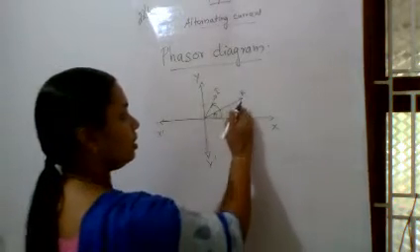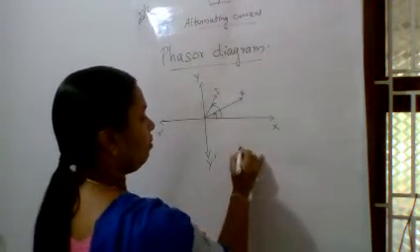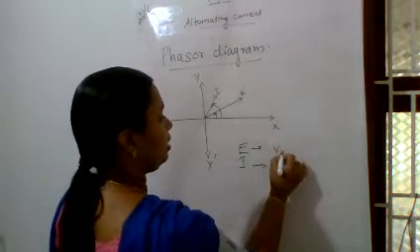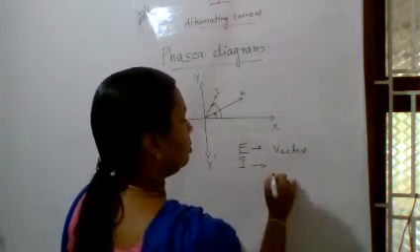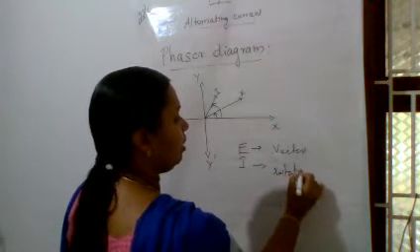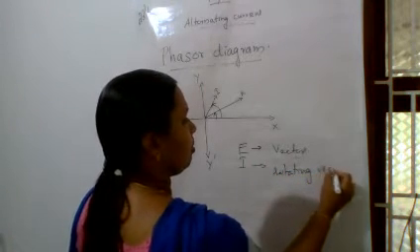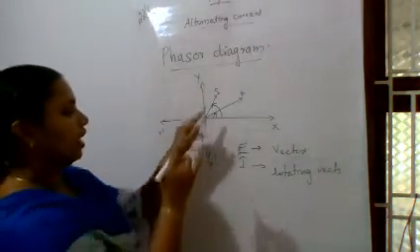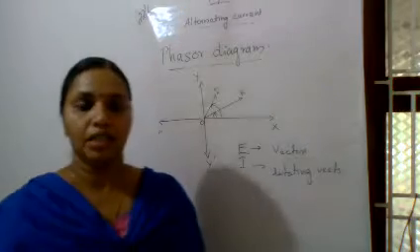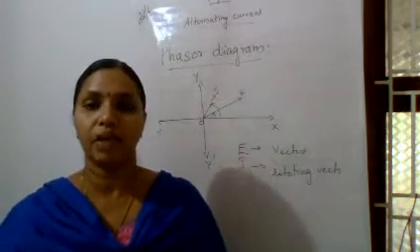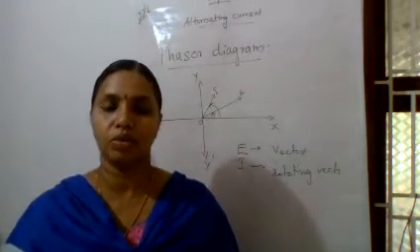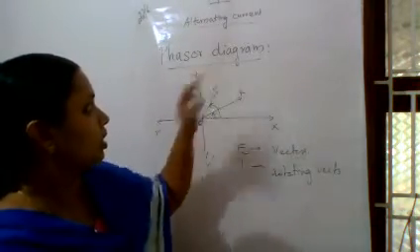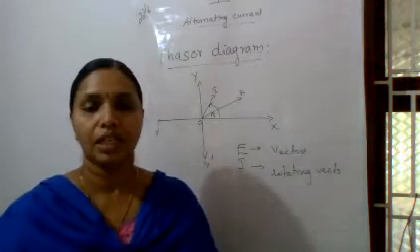We are considering this alternating EMF, E, and alternating current as vectors. And those vectors are rotating vectors. With respect to this origin, they rotate or move with the same velocity, that is, the angular velocity omega. Such a representation is known as the phasor diagram.